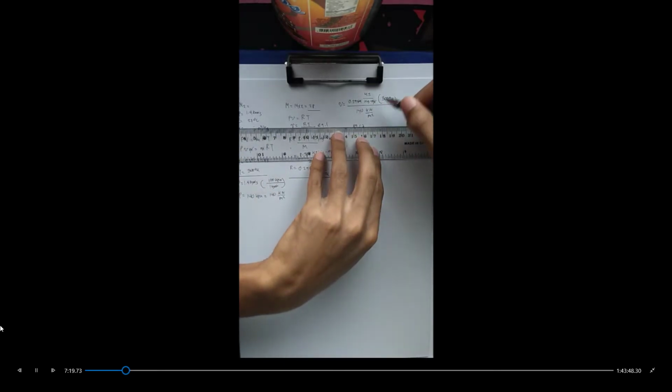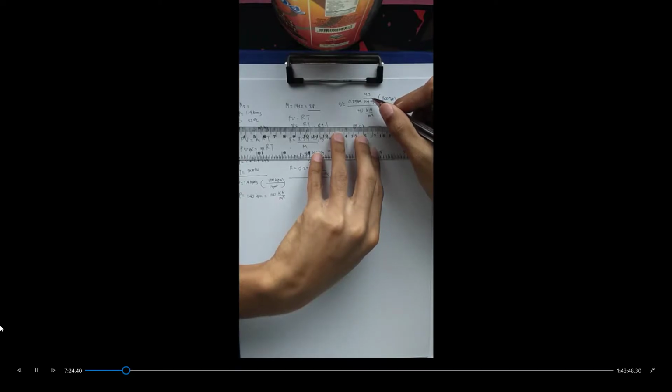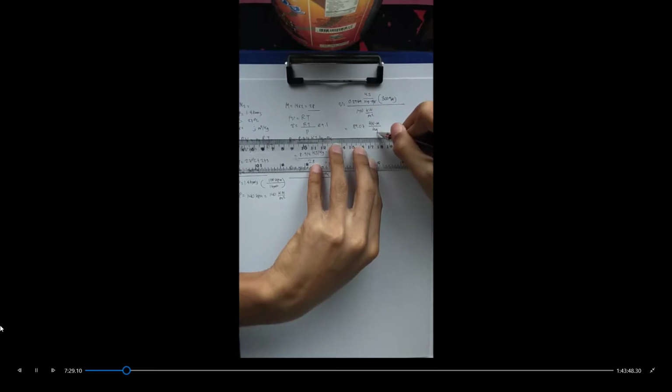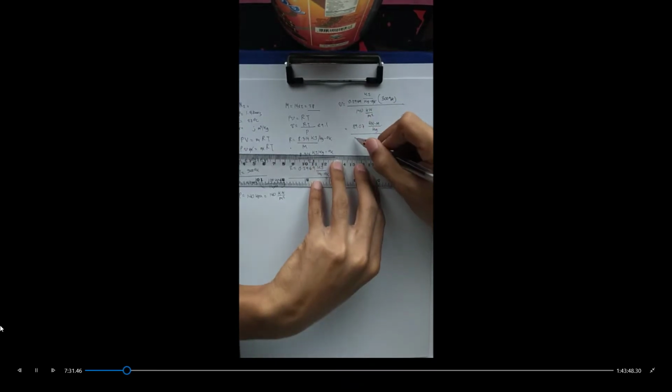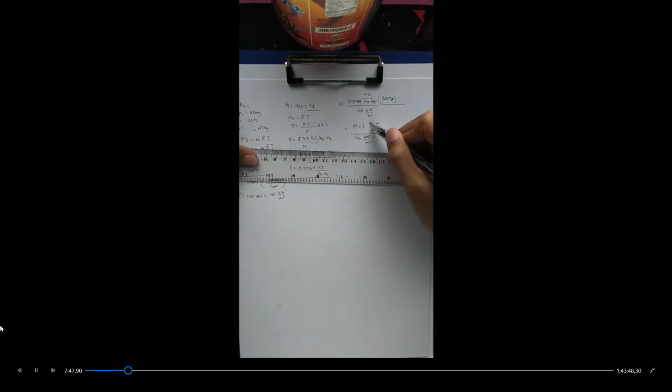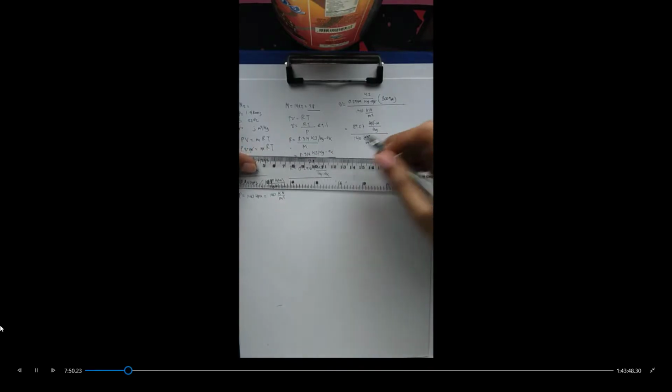So the remaining unit at our numerator will now become, and also we will simplify kilojoules into kilonewton times meter, divided by kilogram, all over our pressure, which is 140 kilonewtons per meter squared. Now, since this is in a form of division of fractions, meter squared will flip to the numerator and be multiplied to the unit of meter at the top, and then we can cancel out kilonewtons, and our unit now becomes meter cube per kilogram.